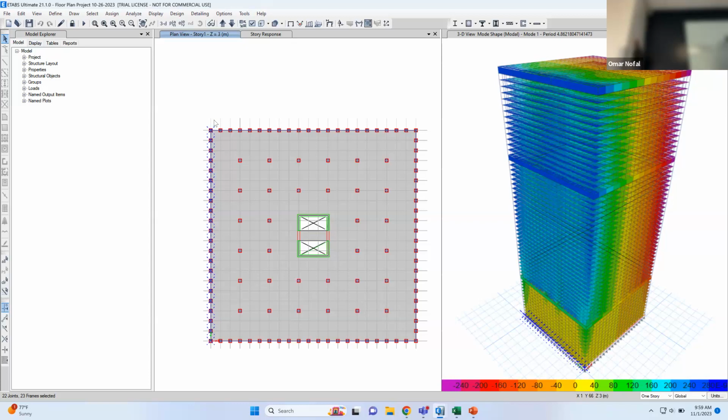All right. So we have two shapes of the shear lag. One of them is changing linearly, something like this, and one is on the other side. If the earthquake is hitting from this side, I'm supposed to see the one that makes a curve like this, because this comes from the load coming this way. If the load is coming this way, that means there is a bending moment this way, and this side has tension and the other side has compression, right?